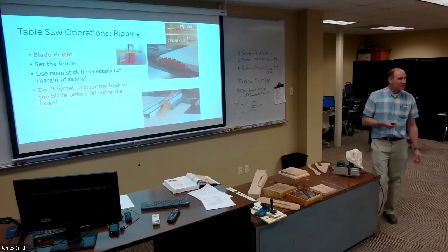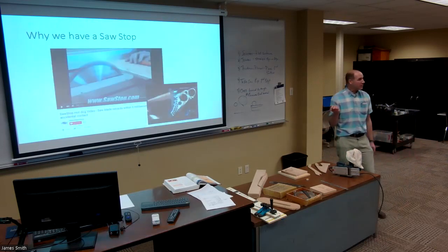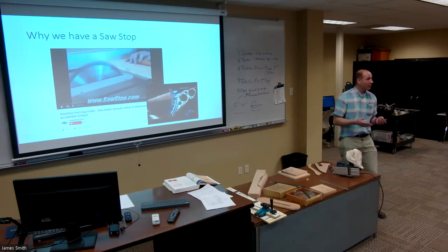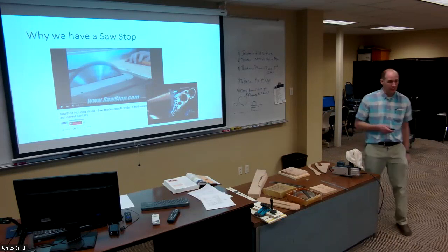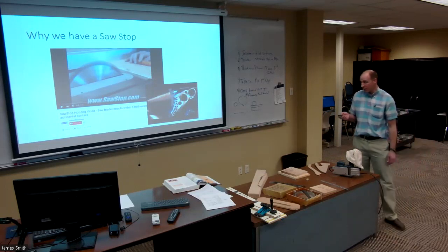But just understand that this is the type of saw that we have. So that also means that we can't cut green wood, okay, without turning that feature off. Okay, we can't cut aluminum. Anything that's conductive is going to set that feature of the saw off. Okay, so even green wood that has lots of moisture content, that's going to set it off. So you have to just run the saw in bypass mode. And there's a trick to doing that. I can show you how to. They're really worth their weight in gold.